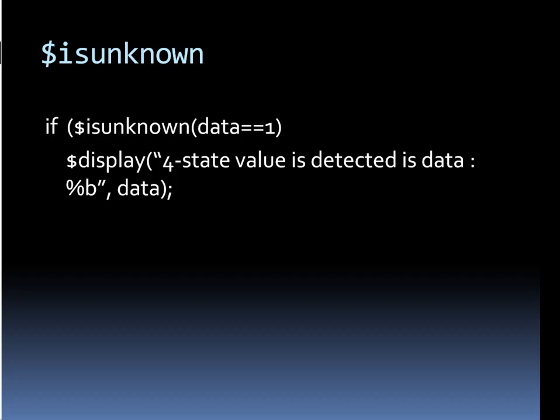If the hardware tries to drive an X or Z in the design, these values will be converted to 2-state values, and your testbench code may never know. So don't try to remember whether they are converted to 0 or 1. Instead, always check for propagation of unknown values. Use the $isunknown operator in that case.